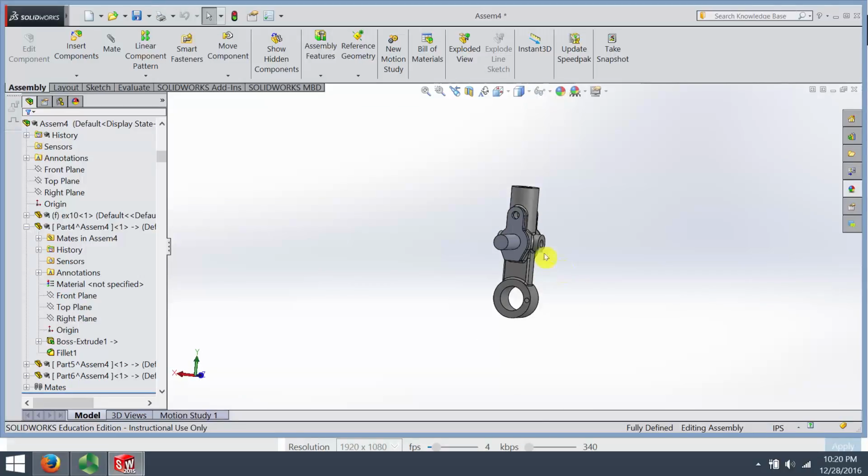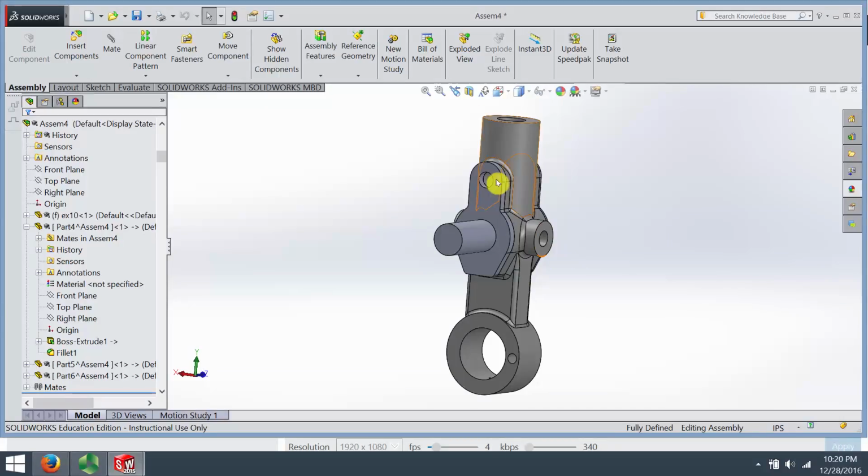What I generally will have students do is find a part that has all these different kinds of mounting surfaces on it, and just grow some parts organically out of it, off of it, in it, that are based on the geometry. The only thing I would have them do that I haven't been doing is, when I make this shaft, don't make it exactly the size of the hole it's going into. Make it a little smaller so we have some clearance. Or if there's anything else that you think functionally, by the fit or the relationship between the parts, ought to be different, then you're going to change that. But even if I used offset, it would still offset from that original geometry, and then if that original geometry changed later in the design, they would update together.